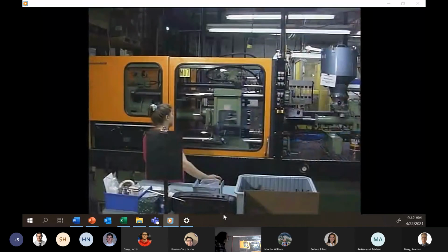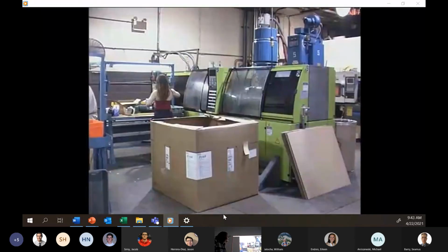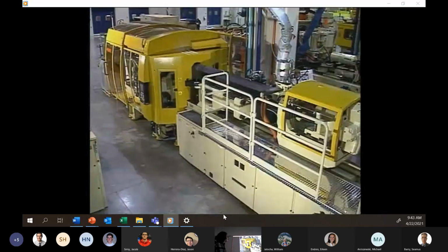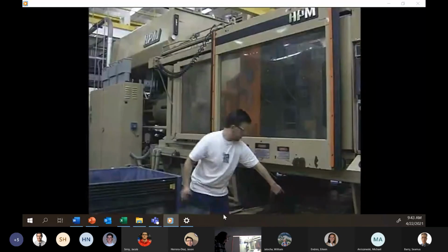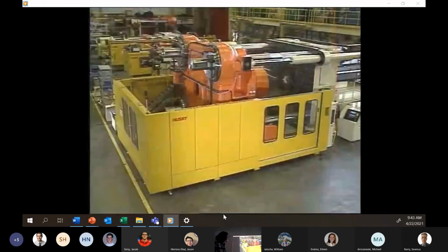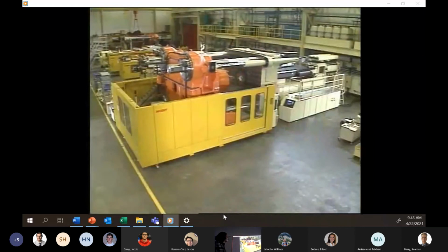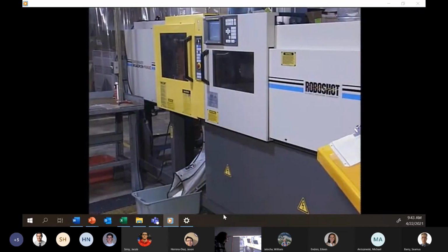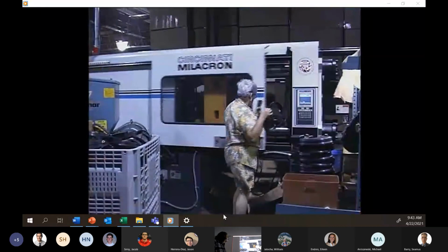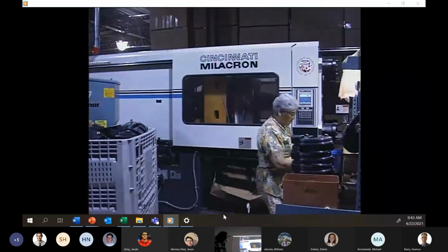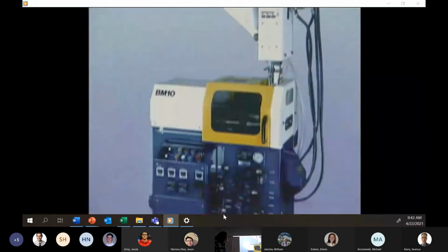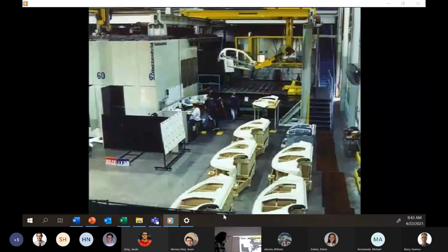There are a variety of injection molding machines in use today. The vast majority of these machines are hydraulically actuated and have 3 platens. But newer styles, such as 2-platen injection molding machines and electric injection molding machines, are now gaining market acceptance. Injection molding machines range in size and complexity from desk-size units up to machines the size of a small house.